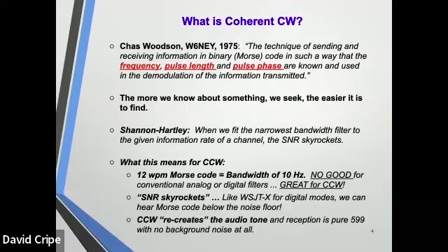You know this when we flip our CW filters on and you go from a wide 2.6, 2.3 kilohertz filter down to a 500 hertz filter, boom, the CW really pops out of there. As I'll show in a minute, if you put that filter down to say 10 hertz,